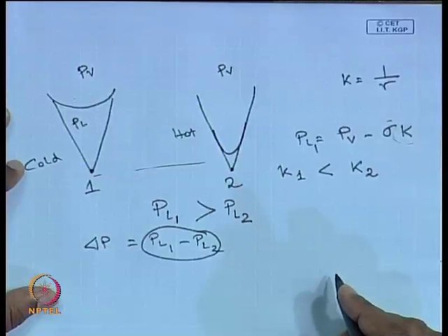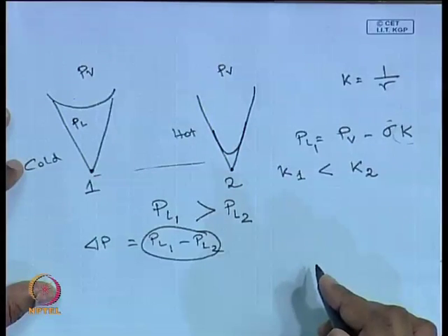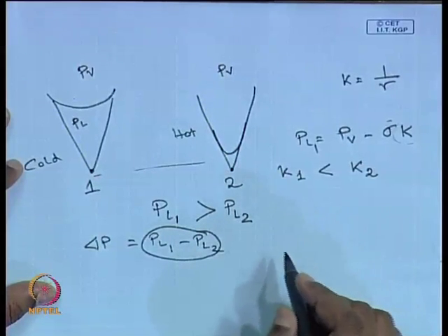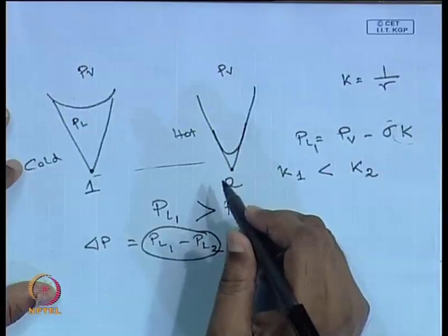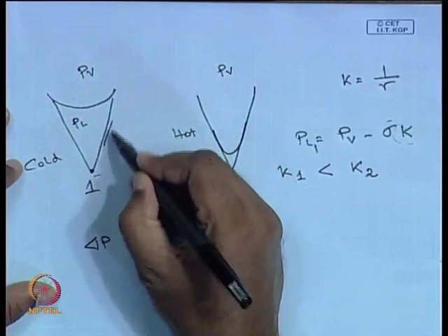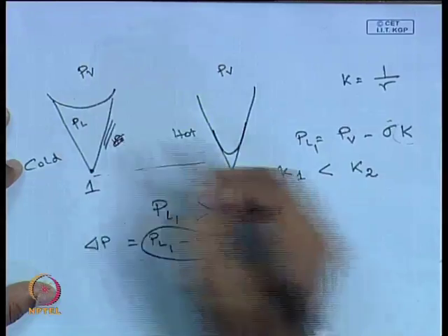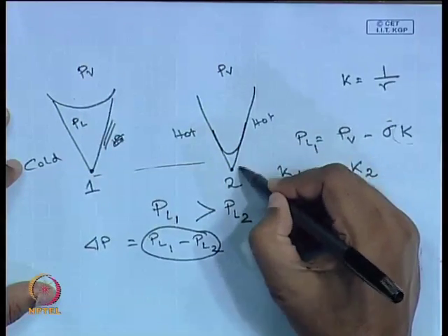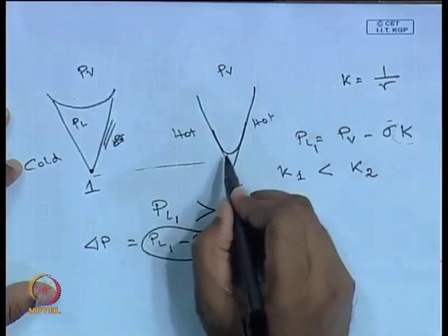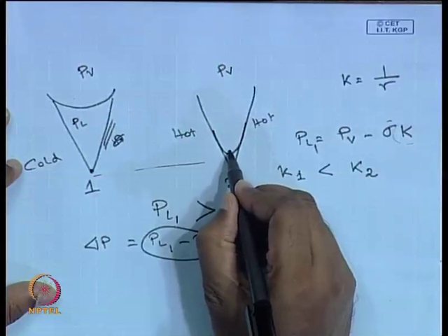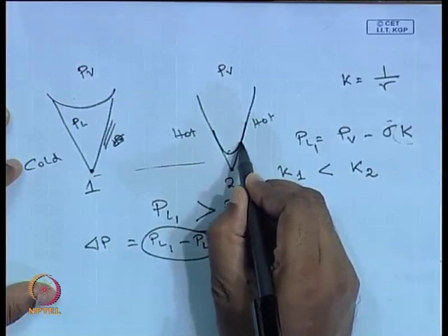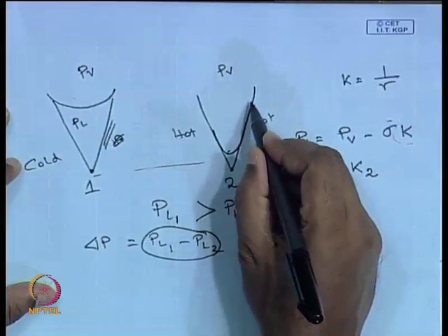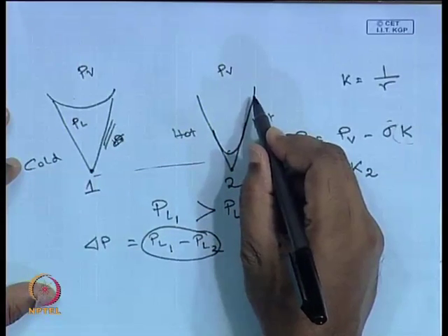Additionally, we were also discussing, and I think we should go slightly deeper into that in today's class, where exactly is the evaporation taking place. These sides are hot, let us say this side is hot. So, the entire solid is hot. So, there is a possibility of evaporation from here as well as from the thin film that extends along the walls of the micro heat pipe.